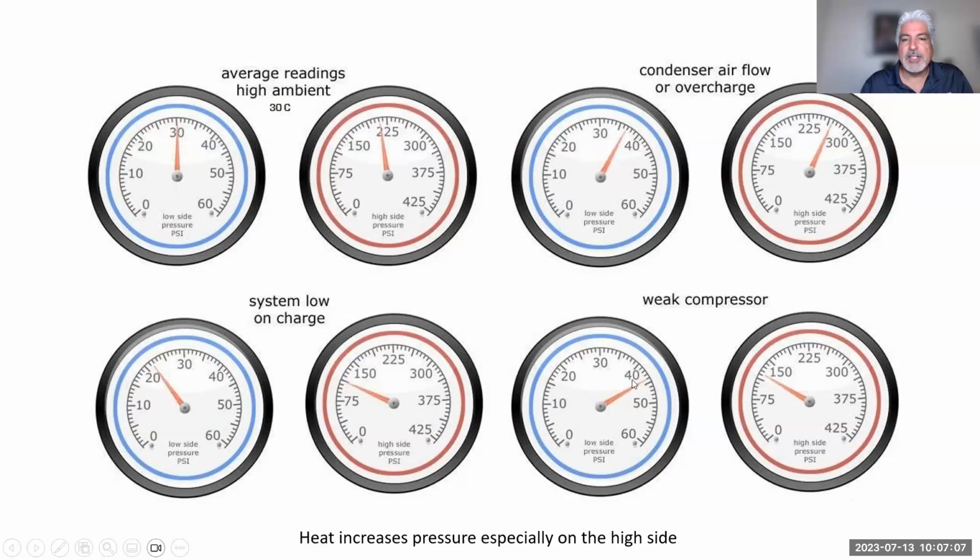So I guess what I'm trying to say is, yeah, this is a very high low side pressure, and this is a very low high side pressure. So we're not pressurizing enough. And again, we're not sucking down enough, because as the pressure drops, we're creating more of a suction, lowering the boiling point. So therefore, we definitely can see that this is a compressor issue.